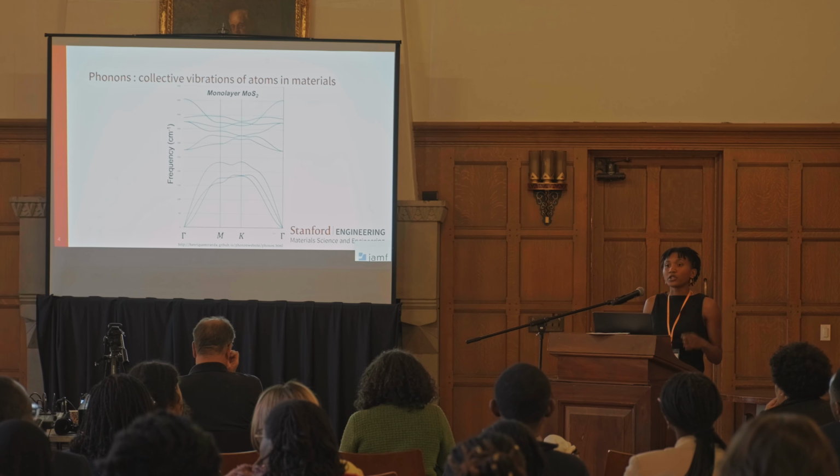And then after that, we can transfer them off, put them on any other substrate that we'd like, and then dissolve the polymer layers used for transfer, and are left with a large area monolayer with nanoscale bubbles and wrinkles. So here what we're looking at is atomic force microscopy images after using this fabrication technique, where the bright areas are the taller areas on the monolayer. And we can see how we can use this technique to engineer these nanoscale bubbles and wrinkles in a wide